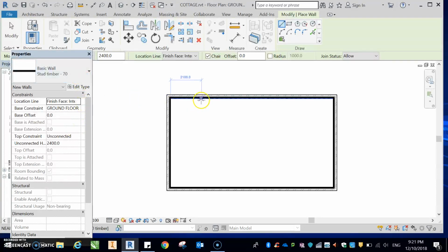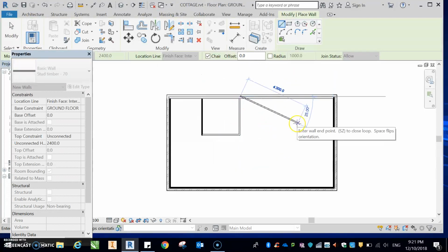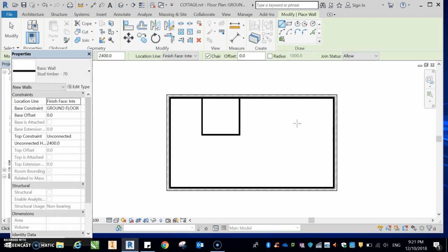So let's have a go at this. I'm just going to click that in there. I'm in line command here. I don't want to use that one because I'm going to put specific rooms in it. Obviously, you'll be working off a drawing of some sort. So if I click on that, I can continue. We're in sketch mode. If I've got a couple of rooms here, I'm not going to leave spaces for the doors or the windows or anything like that because they come in automatically later. I'll show you when you put a window in.